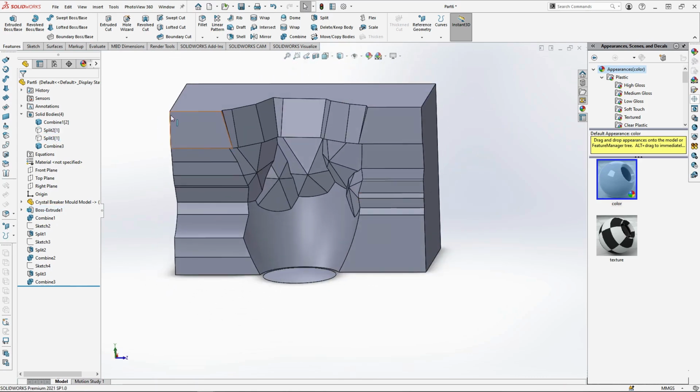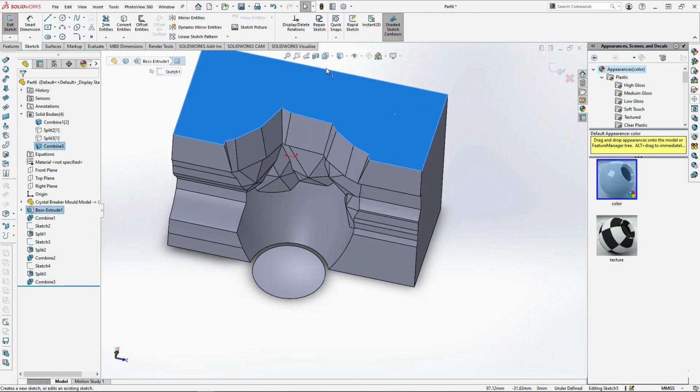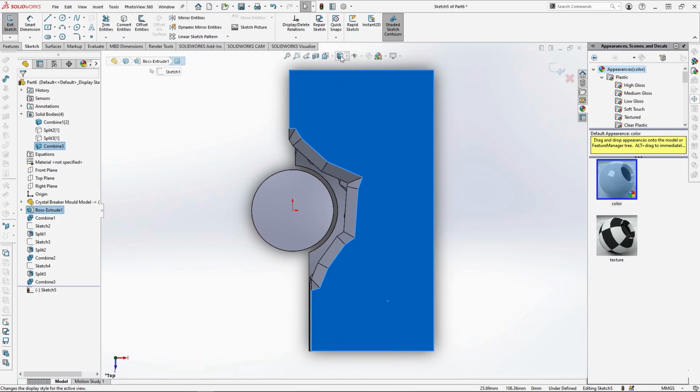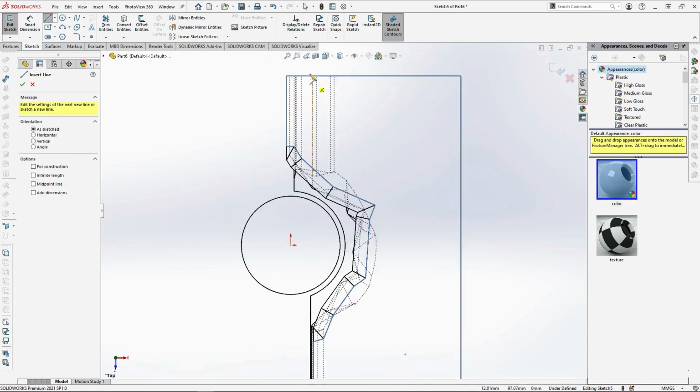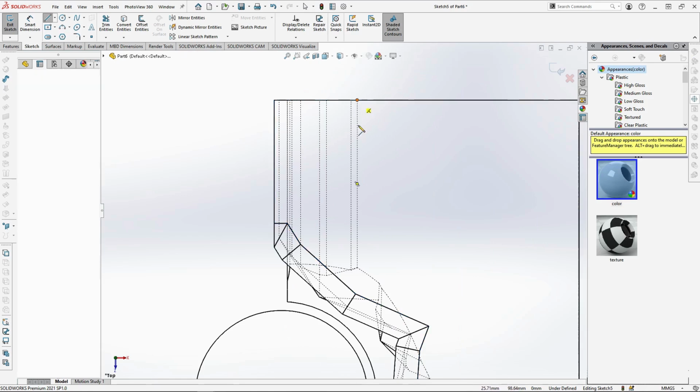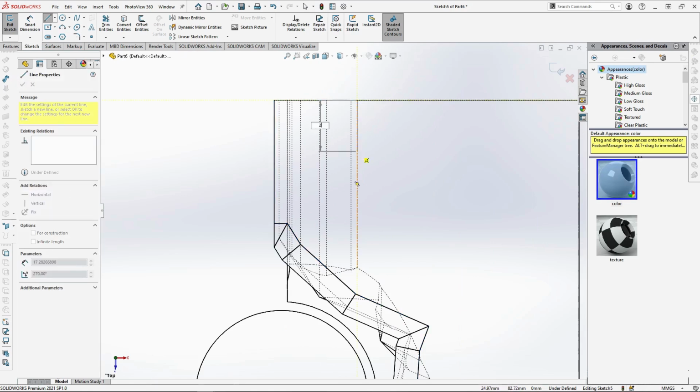need a smoother surface. Notches are for aligning the sections of a plaster piece mould. To do this, start a new sketch on the top face of the mould part. Turn on wire view and with the line, start from the furthest edge in. From the mould edge, go along this edge by 25mm, then diagonally up to the outermost edge.